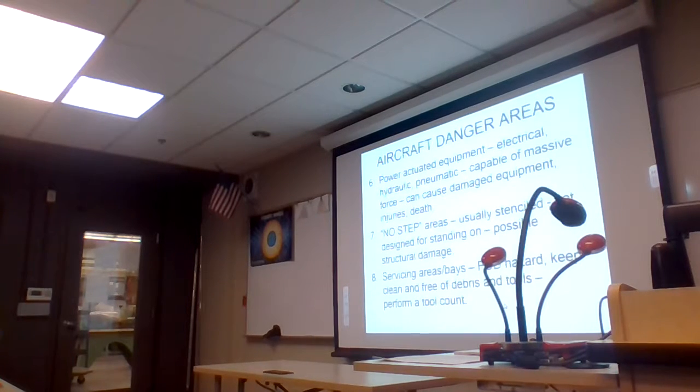Servicing areas and bays. This is a potential FOD area where we have to service hydraulic fluid into a reservoir or maybe service an accumulator. They're usually relatively clean, but sometimes they're littered with debris, safety wire, and a lot of dirt. Sometimes the hydraulic fluid spills and creates a gummy mass that attracts further dirt and debris. So this area should be really clean. What I would recommend, if you use tools, is to always take a tool count. Make sure that you don't leave anything behind. Sometimes it's easy to do, but it's always a possible FOD area.